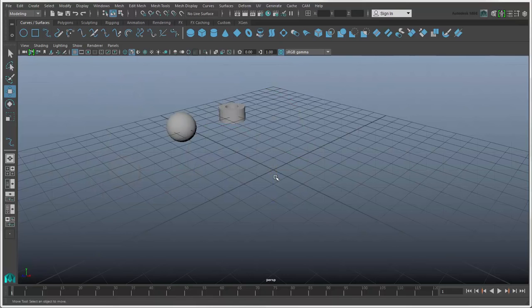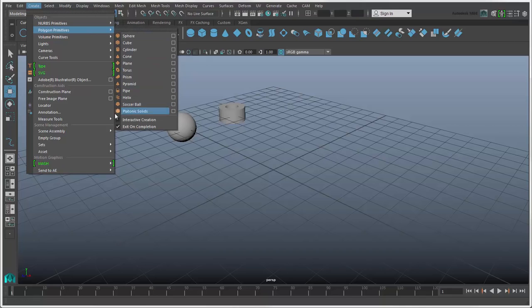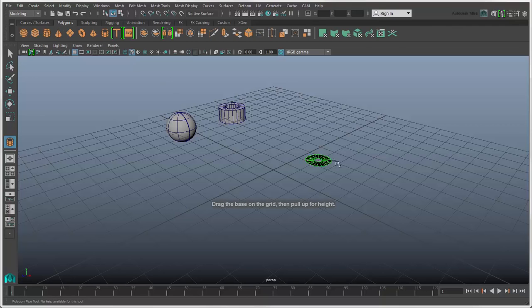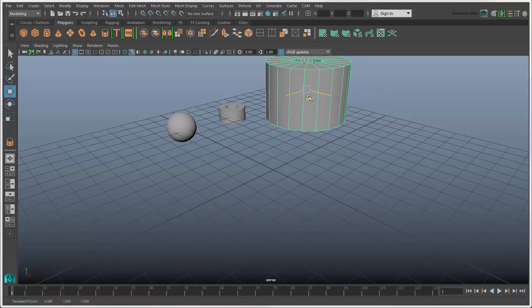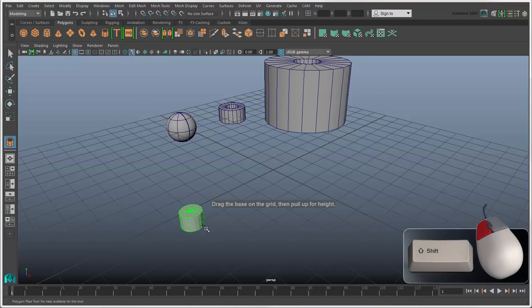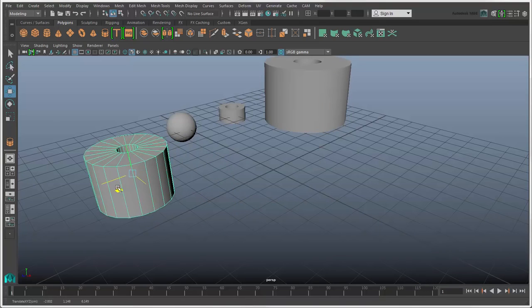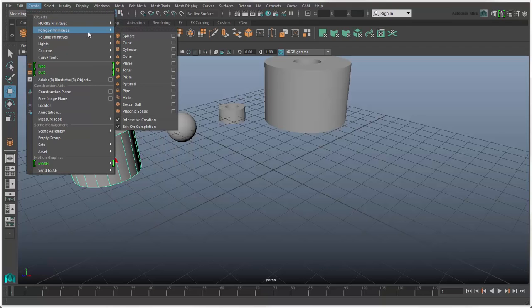If you want to make a custom-sized primitive object, turn on Interactive Creation in the Create Primitives menu, and draw the primitive in the scene wherever you want it and to whatever size you like. You can also press Shift while dragging to grow the object from its base, which keeps it on the grid. Let's go back to the default mode with no interactive drawing.